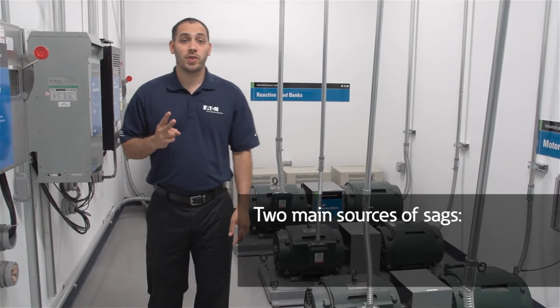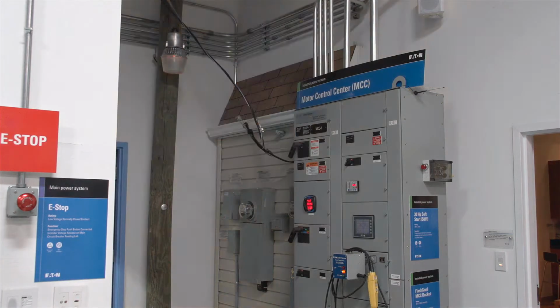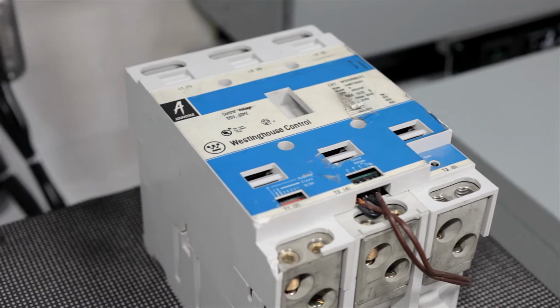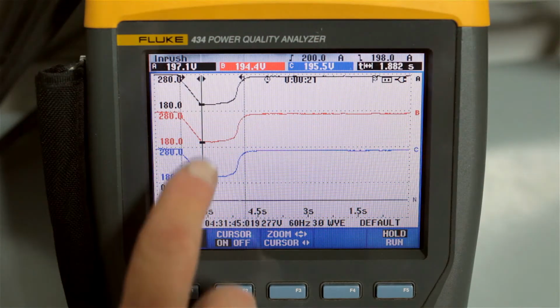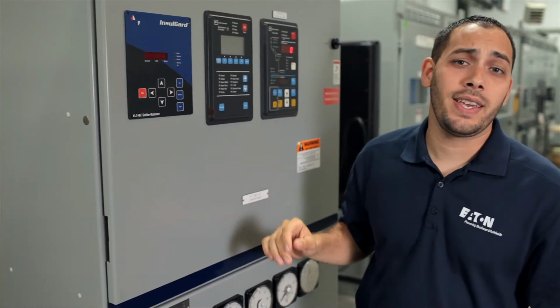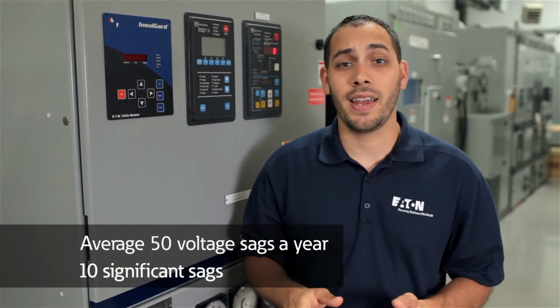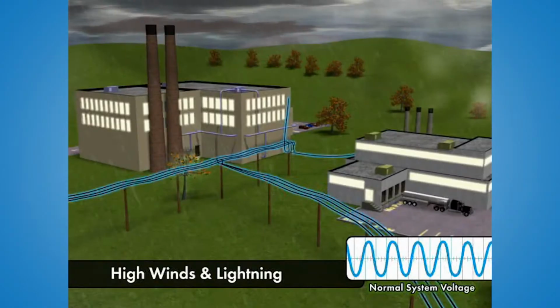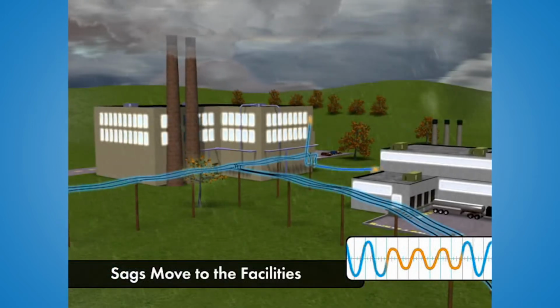There are two main sources of sags: motor starting and faults on the utility system. When a motor starts, it draws a large inrush current, which drops the system voltage. In large processing facilities such as wastewater treatment plants, this happens multiple times per day. On average, a facility gets 50 sags a year caused by utility-related events. Of these, about 10 are significant enough to cause problems within your facility. These are usually the result of high winds, lightning, or animal and tree contact.